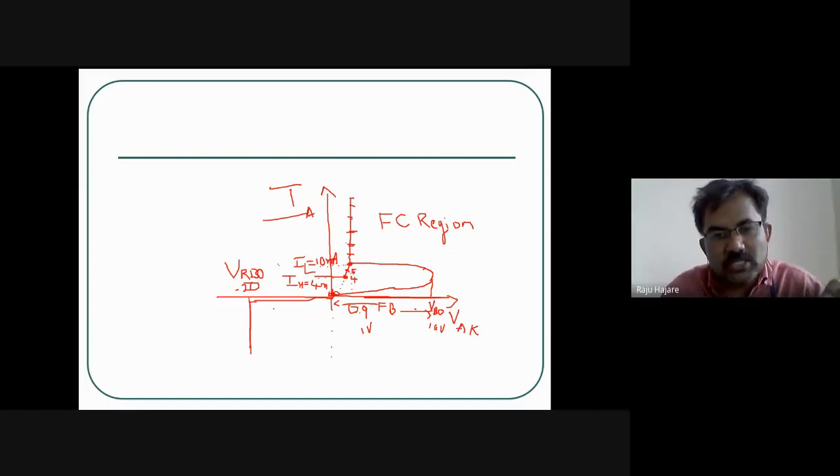Okay, so I am interested in the forward biased condition, forward conduction of the SCR, not the reverse biased case, because that may damage the device. With high reverse voltage, negative voltage, there are chances that the device may go off, and it is of no use. I am only using this as a unidirectional switch, a perfect switch. It works fine for all my applications, so I need not worry much about the reverse bias condition. But when you draw the graph, try to show this.